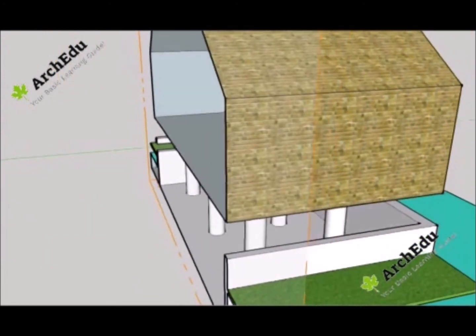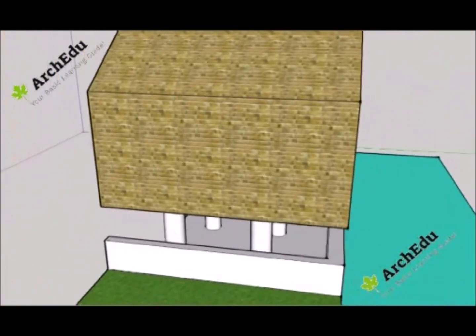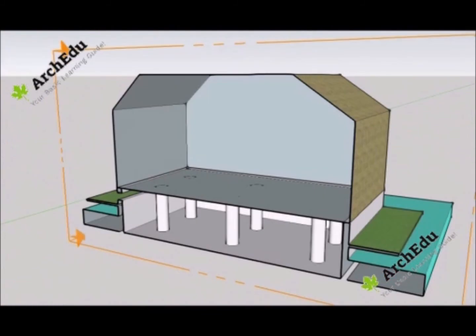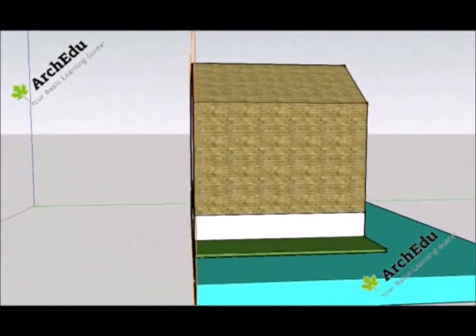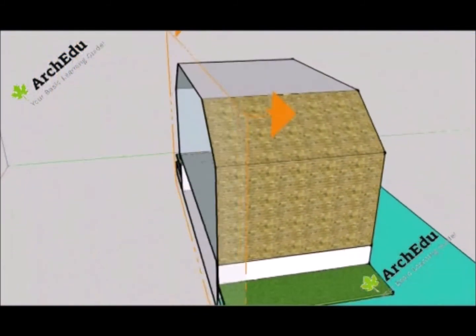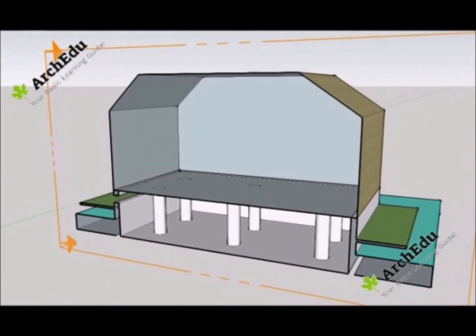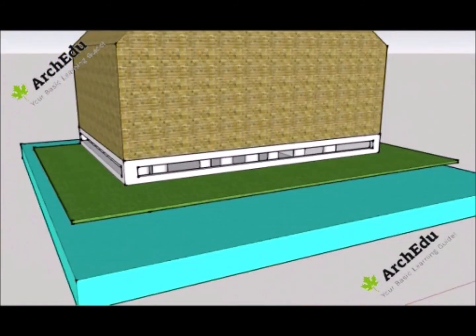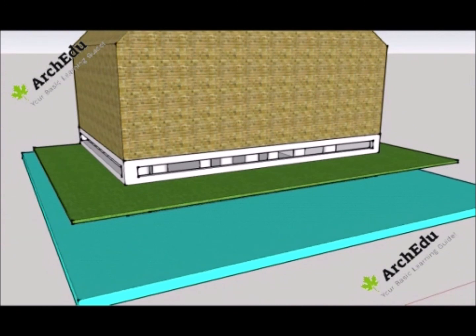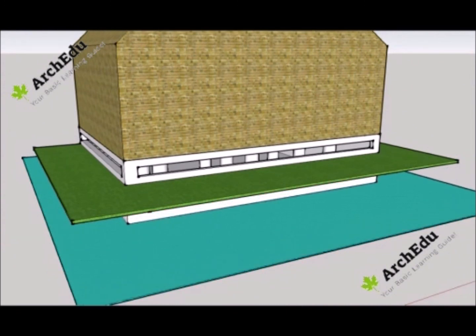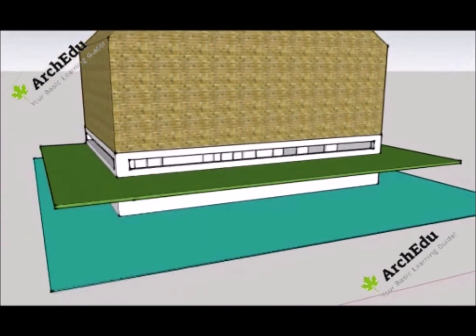The system consists of three basic elements: buoyancy blocks underneath the house that provide flotation, vertical guideposts that prevent the house from going anywhere except straight up and down, and a structural subframe that ties everything together. Utility lines have either self-sealing breakaway connections or long, coiled umbilical lines.